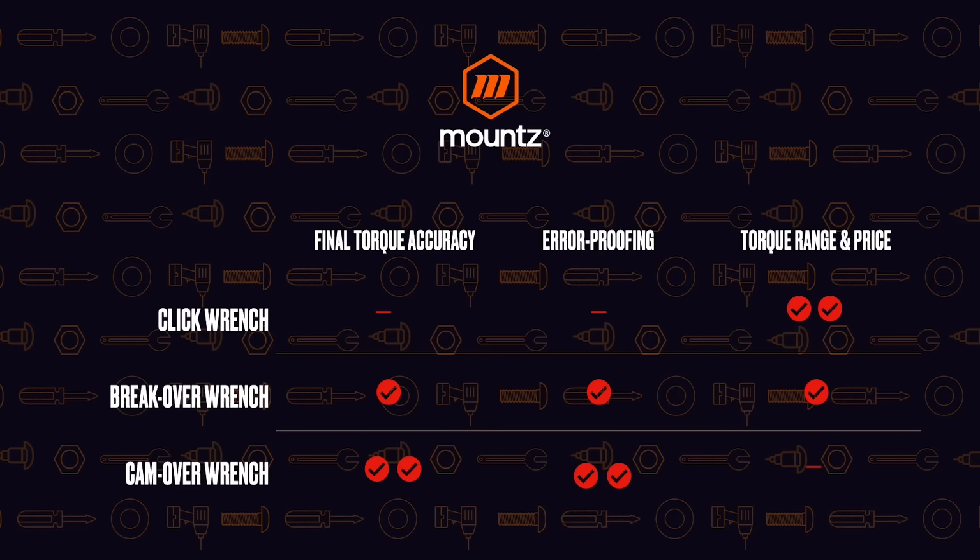For an error proofing type of process, again, the cam over wrench is going to be best for that particular type of operation. However, if you have a specific target of torque or a specific price point that you need to meet, the click wrench again will satisfy those needs at that point.